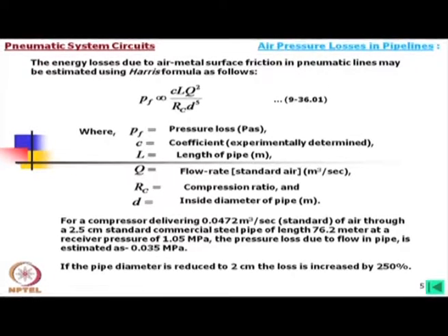But for an increase of 0.5 millimeter in the inside diameter, the quantity of air required will be huge. So, just looking at the point that there will be friction loss for a smaller diameter, we go for a higher diameter. That should not be the attitude. We have to properly calculate what the loss might be, and then select the pipelines.